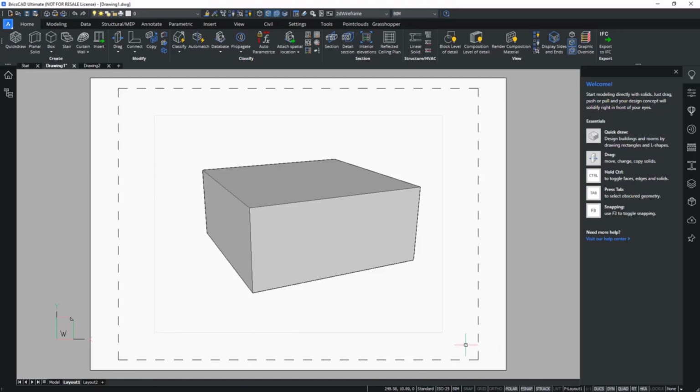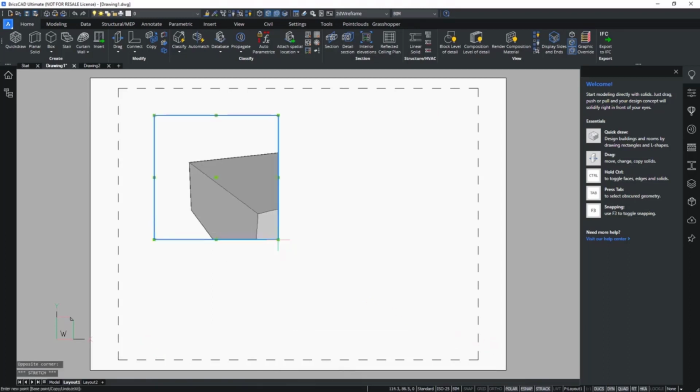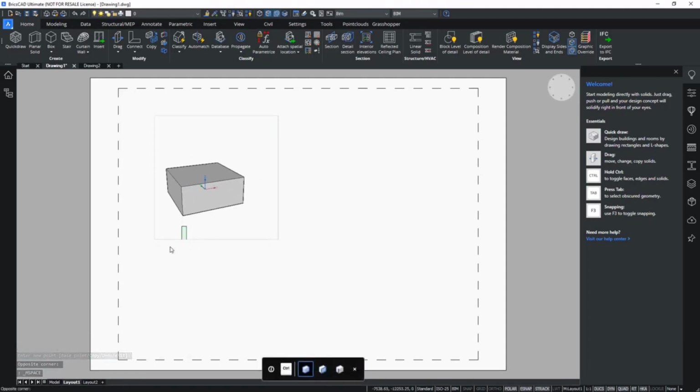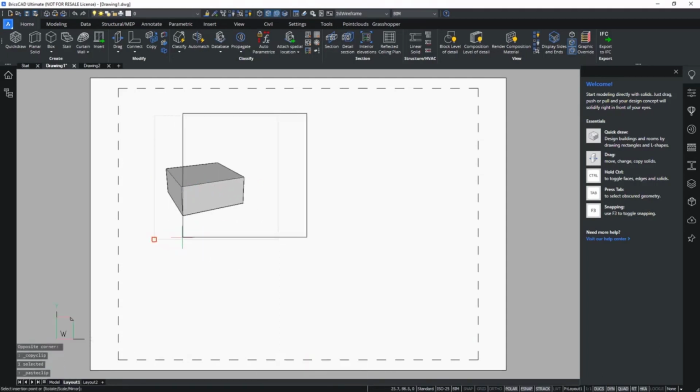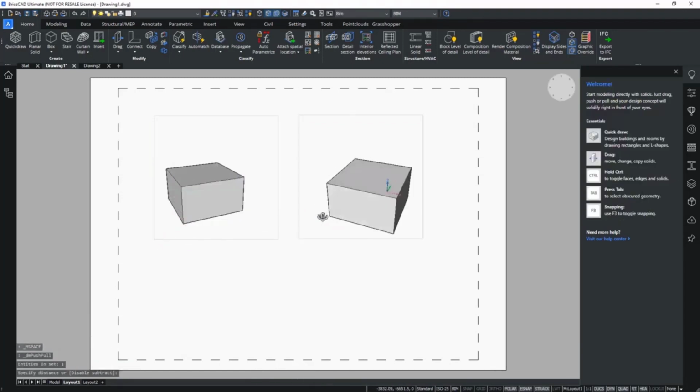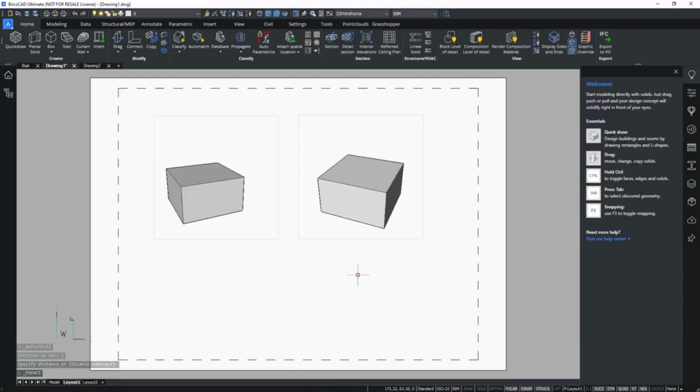So we always make viewports to look onto what we drew in the model space. And you can make multiple views, so we can zoom. And then you can copy the viewport, and you can, of course, make different views onto one paper. So it's literally a virtual paper that we can see, and we are now in the paper space.